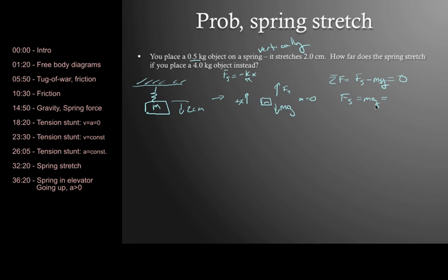Great. So that spring force up is this kx. So here you can go, well, why did I drop this minus? I should just stick in a minus here. That minus is to let me know which direction this spring force is in. Here I've already told myself from this free body diagram which direction the spring force is in. So that's why you don't see a minus thrown in here. So we can work out what that spring constant is, and that's just mg over x. And I'll find that this is about 250 newtons per meter. Great.